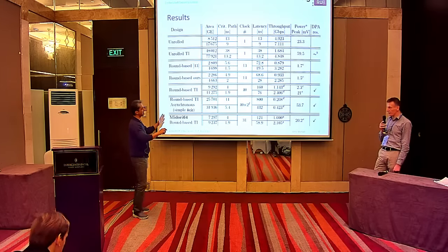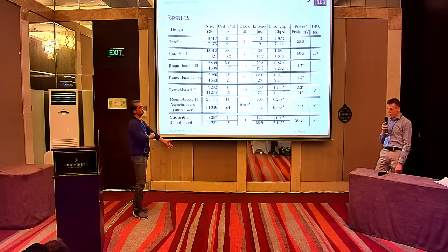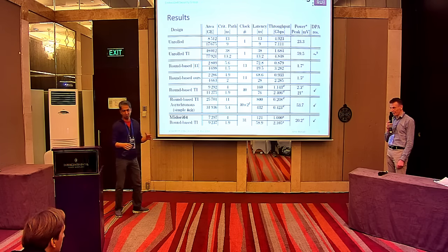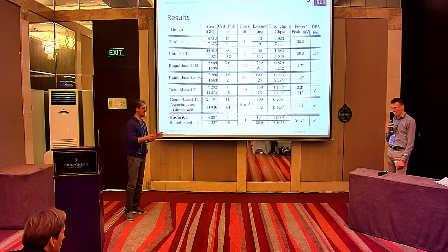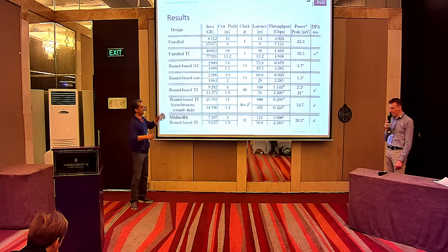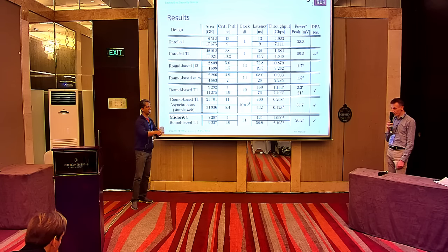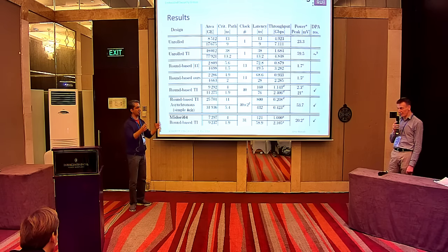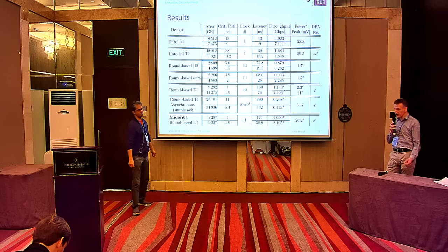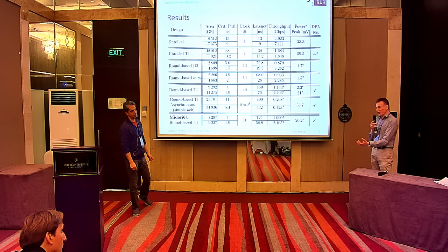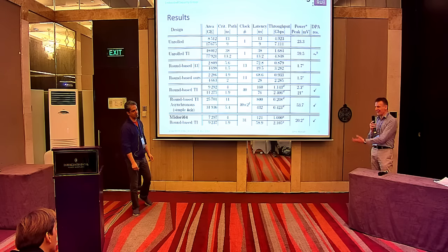Yeah, this is clear. But the security analysis, I would say we can trust that, with the FPGA design, because we were misusing the FPGA elements. For the asynchronous circuit in particular, we were using every loop as a single gate to realize everything correctly. And then I would say the side channel leakage we measured should not be much different from the ASIC one. And are there no ASIC tools that would allow you to do analysis, using tools rather than a real circuit?